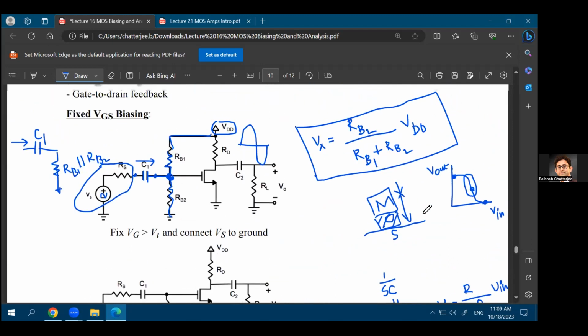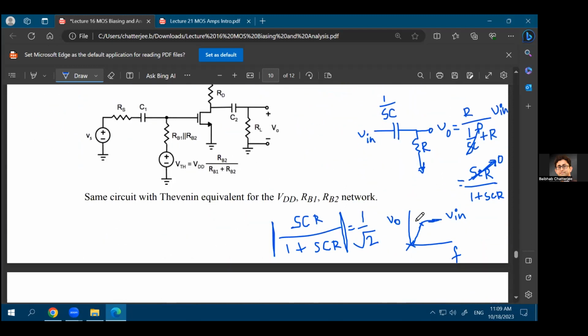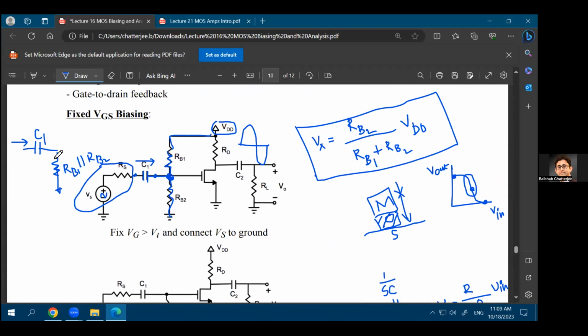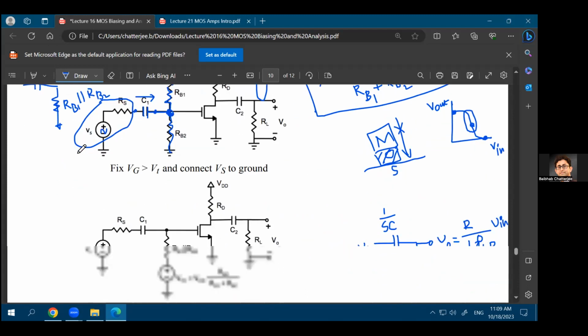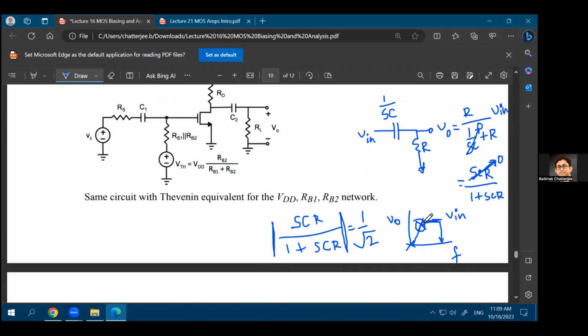All right. So why we are discussing all of that is just because if your frequency is beyond this cutoff frequency of the high pass filter, if the frequency at which you are operating, so let's say this is the frequency at which you are operating, the output of your high pass filter will be equal to the input of your high pass filter, because as you just saw, the transfer function will be equal to 1 at that very high frequency.